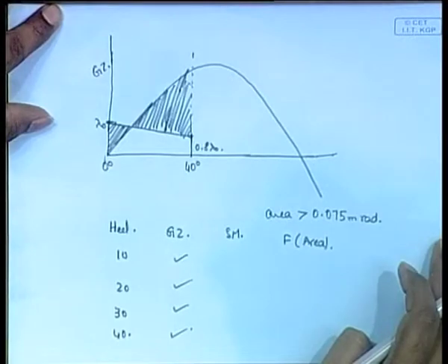Actually, I think it is because one of the rules always in ship design is that the GZ curve maximum should always occur at less than 40 degrees or 35 degrees or something, that is a rule.